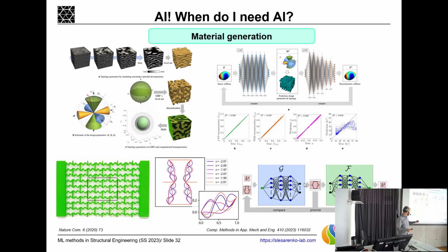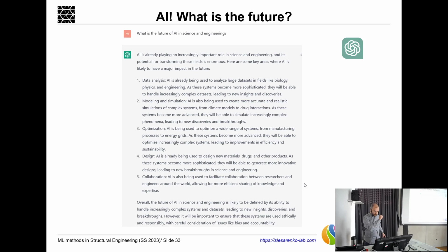So what you can do with these approaches, with generative design, is actually design, let's say, porous structures or two-phase structures that will have a very specific stiffness matrix, if you remember from micromechanics. So you can really say that I would like to have a material that is very stiff in this direction, but extremely soft in these directions. And with generative design, you can do that. This is right now very often used in medicine for implants, because this is a very common topic.